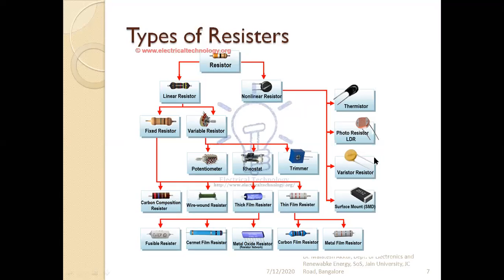These relay systems can be controlled by the controller with a very small voltage, just 5 volts DC or 0 volts. To switch off the AC or any device, the microcontroller sends 0 volts on a particular pin or port. If it has to be on, just 5 volts DC, and that drives the relay through a relay drive circuitry. We're going to see all those in detail. I'm just giving an overview of how we can use the sensors and so on. That's fine.